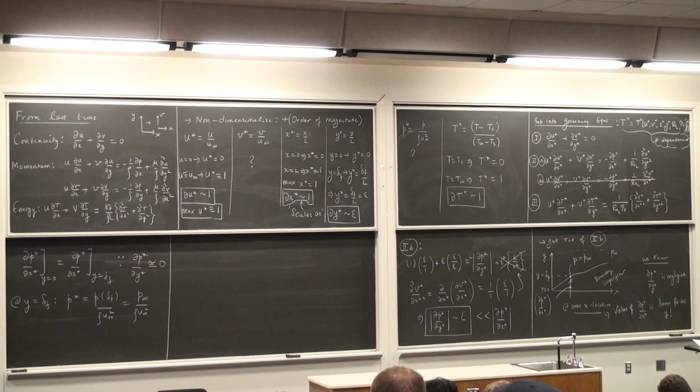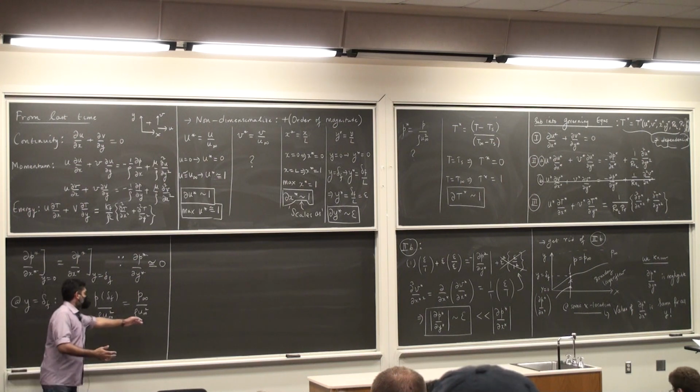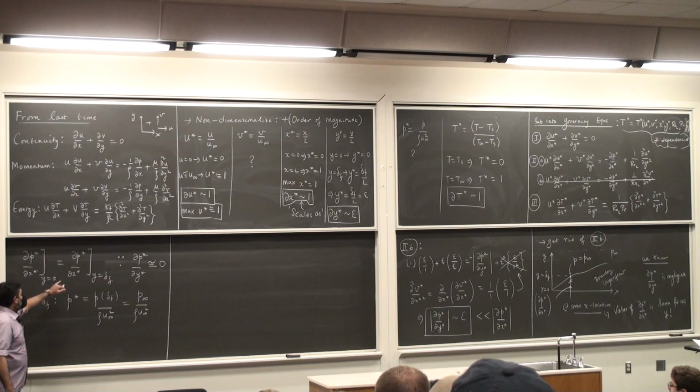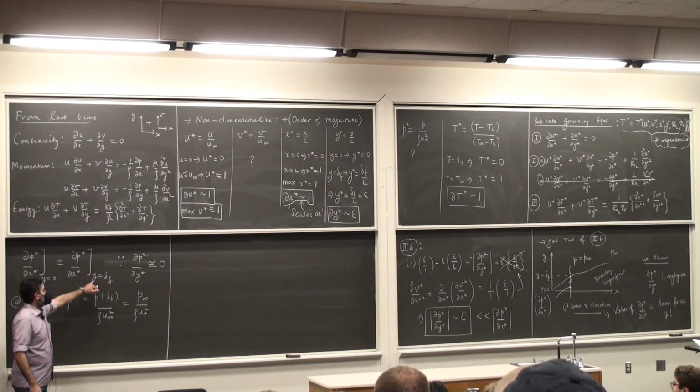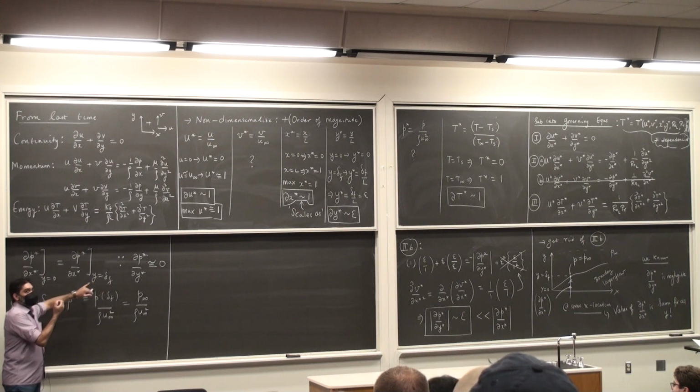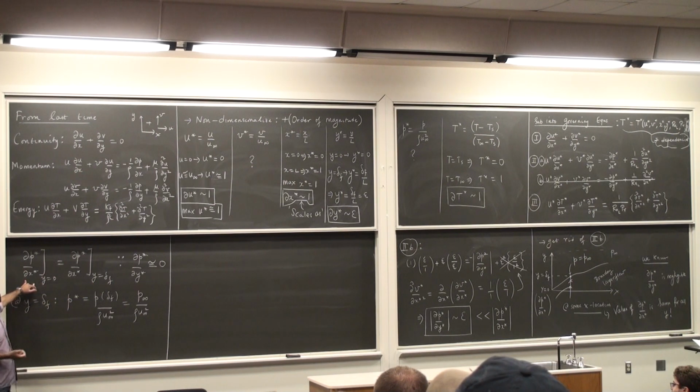Which is the free stream pressure. Free stream pressure is a constant. U infinity square is a constant, rho is a constant, which means dp star by dx star at y equal to delta f is 0. Which means that dp star by dx star everywhere is 0. And so we completely discard that creature out of the game. So now the pressure has gone for a toss, does not do anything to my life anymore.